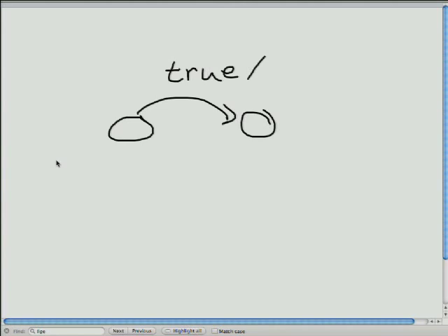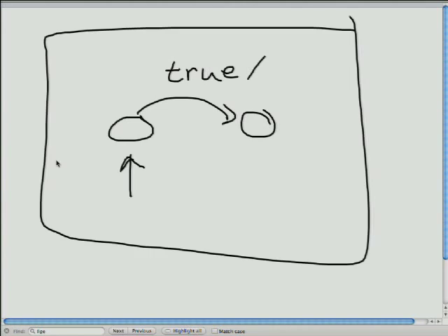Couldn't you almost use this state machine notation as a way to characterize the timing? You can, in fact, and we're going to do that. I'll show you how to augment these state machines with continuous dynamics, and we can build what are called timed automata, which are in fact very compact descriptions of fairly complicated timing behaviors. Okay, so we're going to do that.